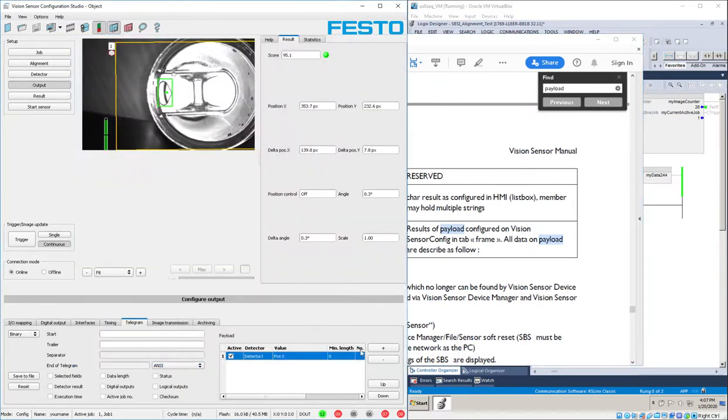So if I had another one, like let's say detector 1 angle, where will this one start? 248, right? Because this one is 244, 245, 246, 247. That's 4 bytes, and then the next one is 248. That's where this one will start, and so on. The more you add, the more offset you're going to have. That's basically how this telegram works.